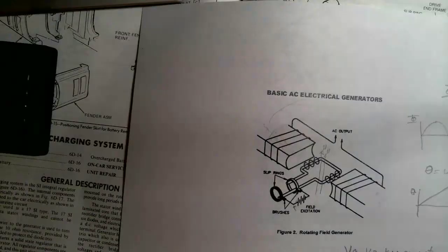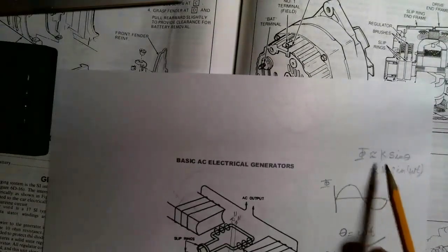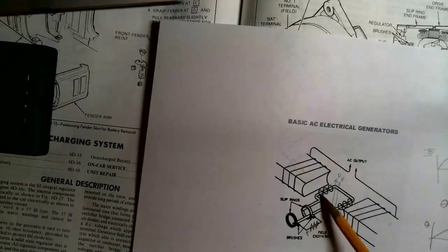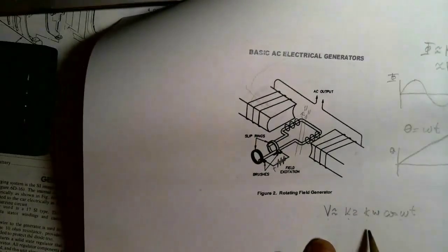there. And how strong this flux is, how strong this flux up here is, one of the things that goes in this K is how strong is this magnetic field. So that flux is proportional to what kind of current we had flowing in the rotor here. And then you notice another factor here is this omega that comes out in front when we take the derivative. So because the voltage induced is proportional to the rate of change of flux, omega, the rate of rotation, directly